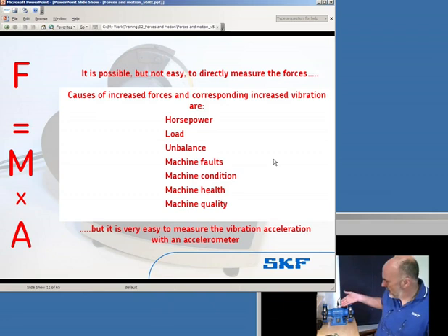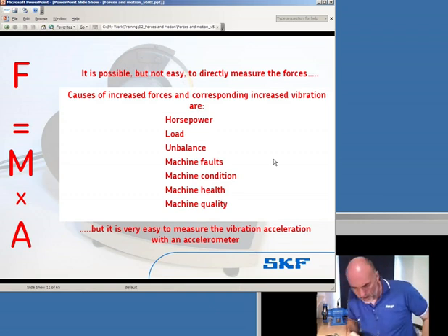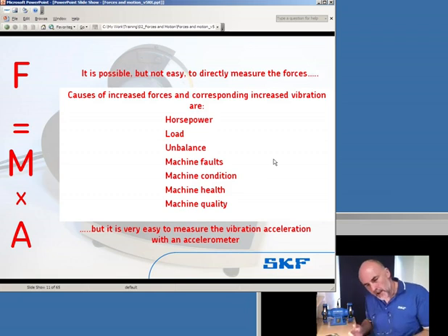A bigger machine, even if it's a good quality bigger machine, is going to have inherently greater power, and therefore I expect to see inherently larger values. And if you take this right out to industries where you've got 15 kilowatt motors, 150 kilowatt motors, 100 megawatt generators in power stations, you expect the levels to go up pro rata, or proportional to the size of the machine.